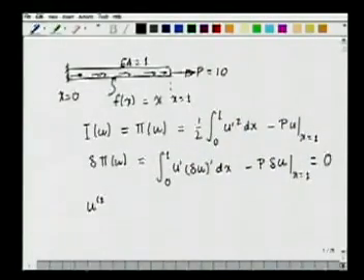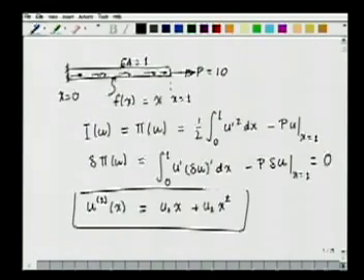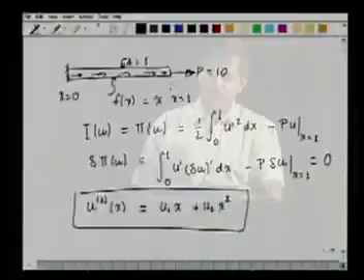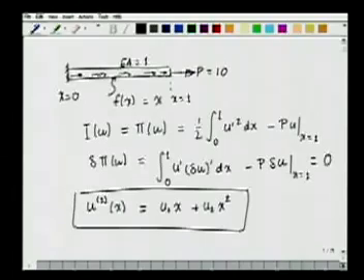Then we went ahead and used a series representation for u. We said that we will take a so-called two-term solution, u2(x) equal to u1 x plus u2 x squared. This is a two-term solution that we took. Why did we take it of this type? Because we wanted this u2(x) also to satisfy the specified geometric conditions at the point x equal to 0. And as you see, here x and x squared vanish at the point x equal to 0.